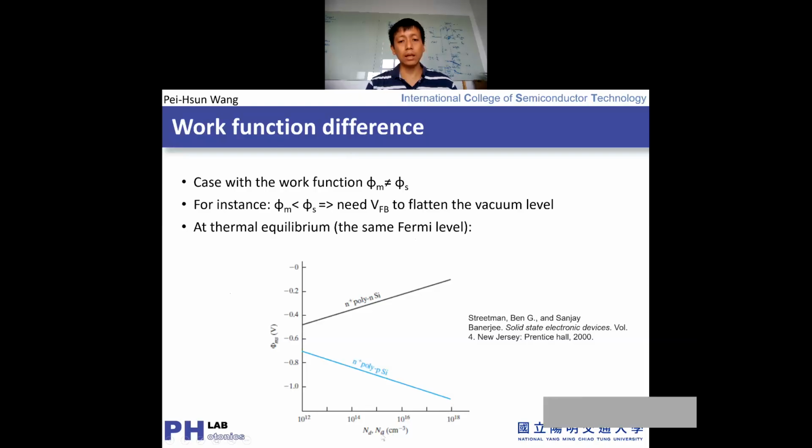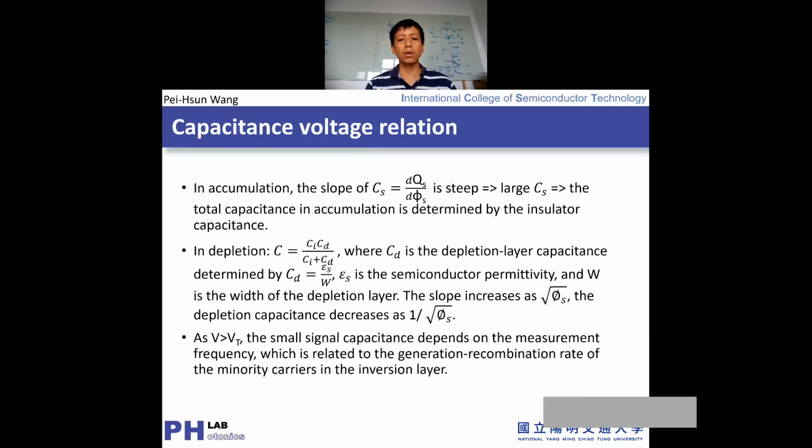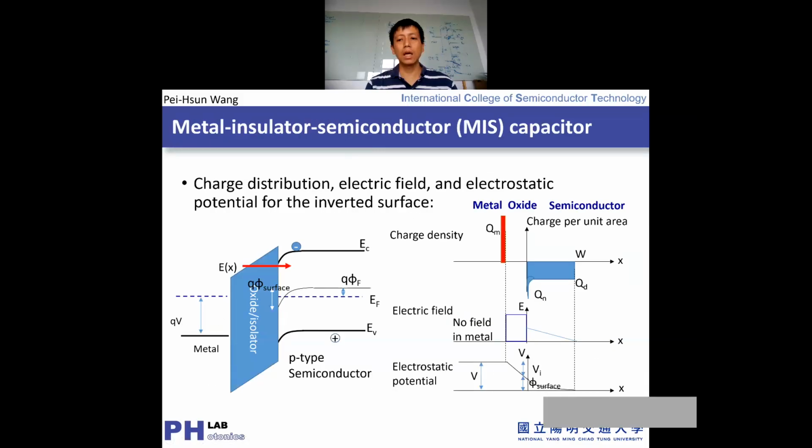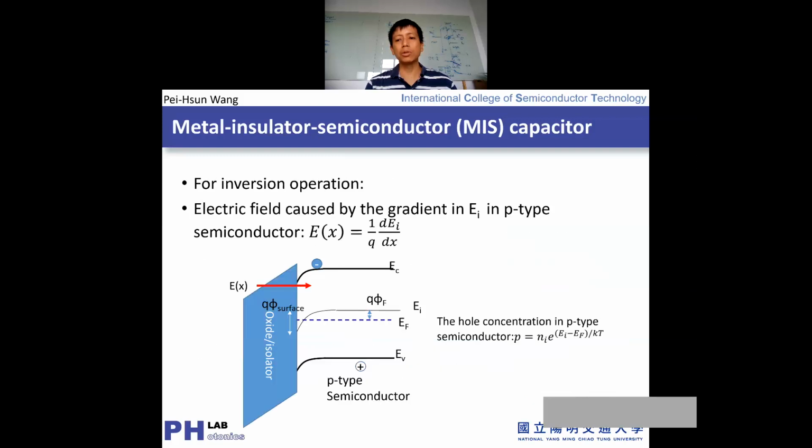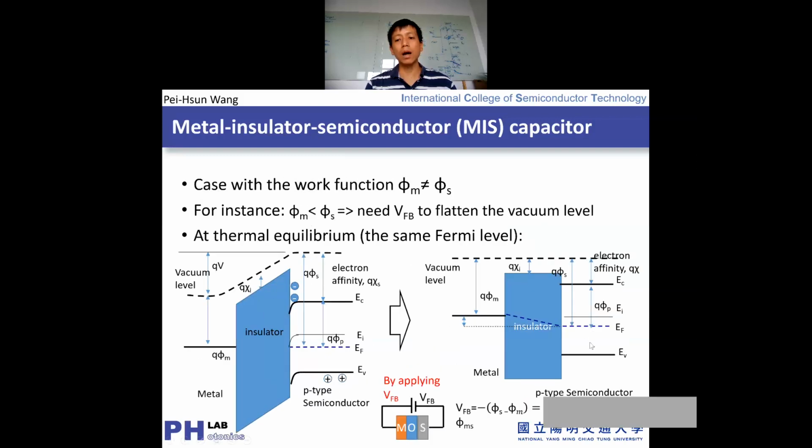So we consider the acceptor. So here's the donor and the acceptor. If you consider the n-type regions, you get more donors. If you get p-type regions, you get more acceptors. So you can shift your Fermi level. If you go back to the previous slide, talking about the flat band voltage, if you get a more p-type region, it moves the Fermi level down along the valence band.